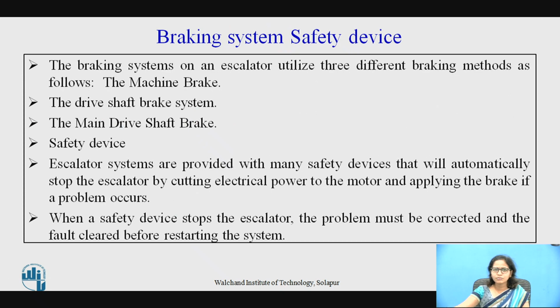So the braking system and safety device. The braking systems on an escalator utilize three different braking methods. One is the machine brake, second is the drive shaft brake system, third is the main drive shaft brake.